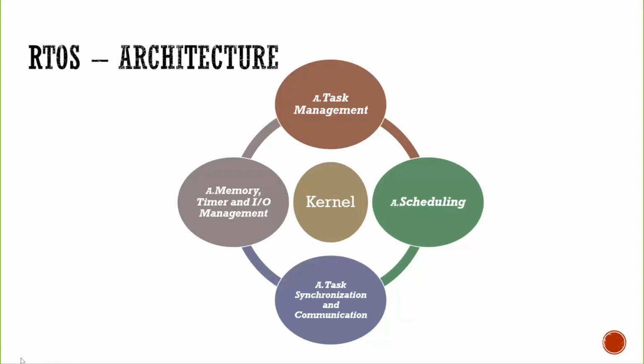As mentioned, tasks are the decomposed, schedulable, and sequential processes that form an application. Tasks are ruled by three time-critical components: release, deadline, and execution time. When an application is executing, individual tasks are concurrently changing state. However, only one task can be run at a time. In the meantime, context switching happens in the CPU to interchange between tasks.